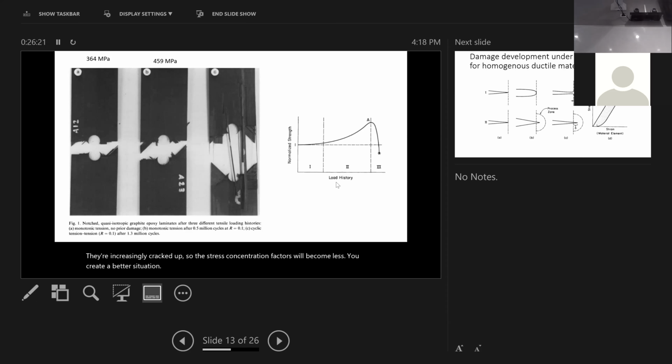But if you keep going, you keep the 80% stress, and then you go for 1.3 million cycles, it breaks itself. So that's a wear-out process. This is a complication of fatigue. You don't see this in metals. Metal doesn't show this behavior. They go straight down. They don't become stronger over time. The composites could initially go stronger, to 1.2 million cycles, and then you keep going. Eventually, it becomes weaker and dies.